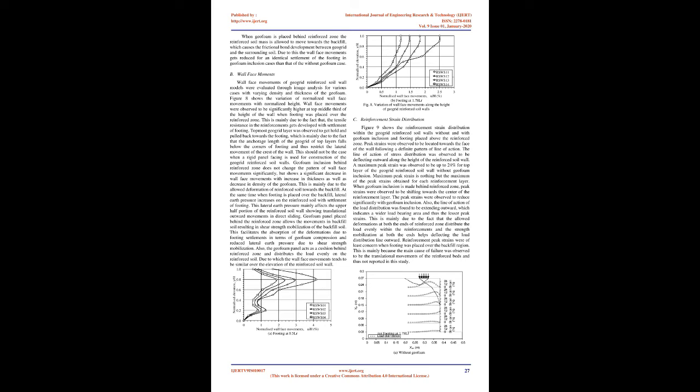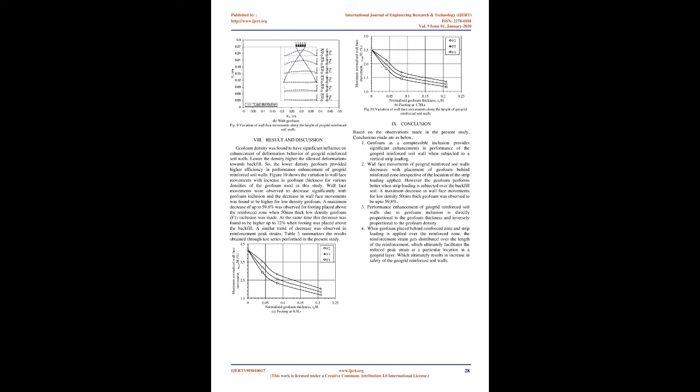of the test. A constant height of 0.24 m was maintained for all the geogrid reinforced soil wall models tested in this study. Reinforcement length of 0.7 h and reinforcement spacing of 0.083 h was adopted for all the reinforced soil wall models. 3 different geofoam types were used in the present study, which were placed behind the reinforced zone with varying thickness and density under the particular test legend.